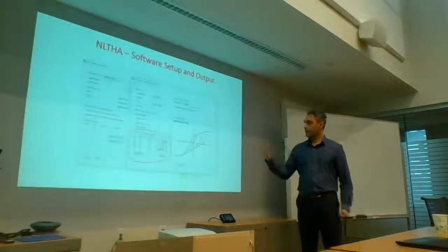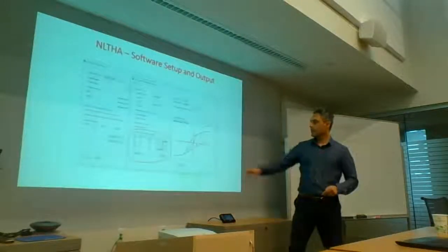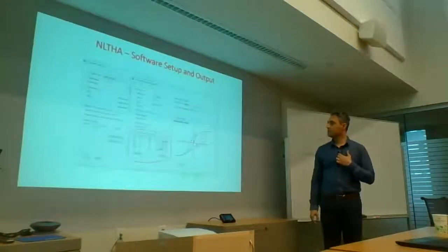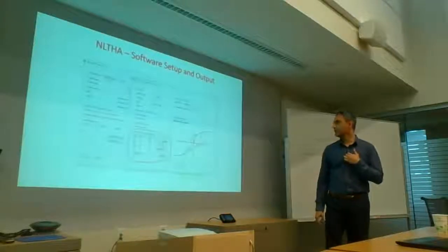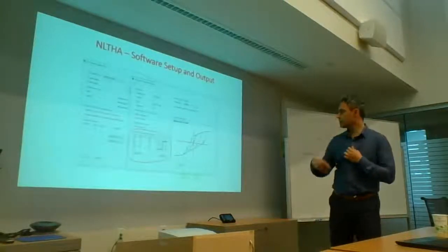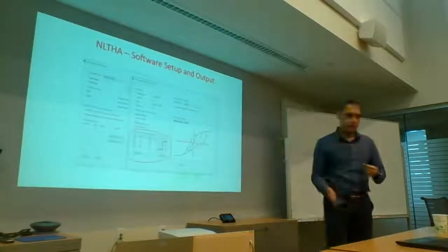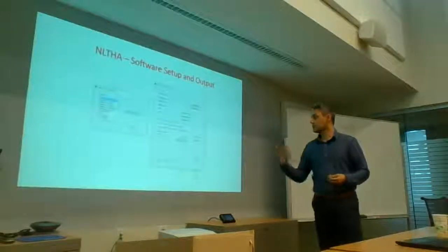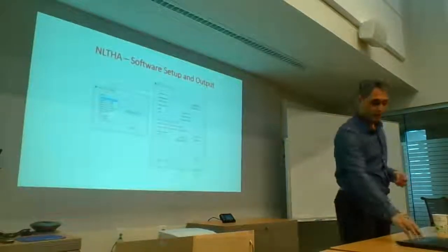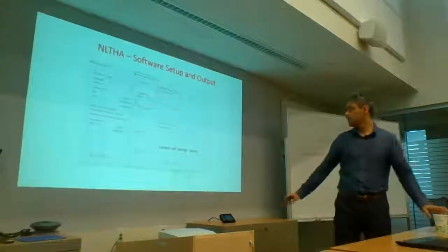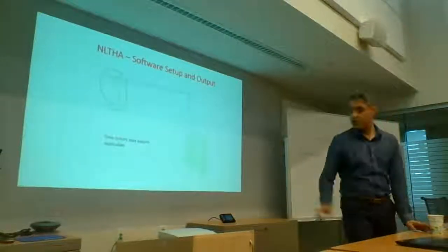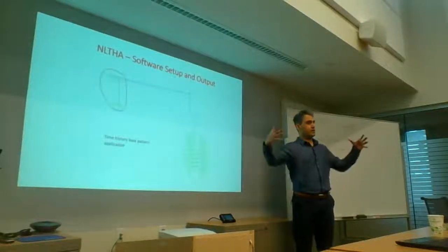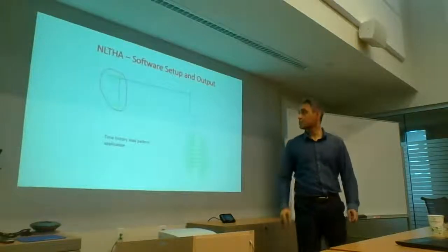And then we had the elastomeric bearings. So we gave the property of that, and then this was more of a hysteretic rule. We put a multilinear plastic kinematic hysteresis rule there, so that when it's unloading, it's coming down on a different path. The only reason I'm showing you this is you can model a lot of these different things. We had caissons there that were very, very stiff. And these are the two caissons. We wanted to make sure that these caissons, which had no reinforcement and were just big, wouldn't just fail.